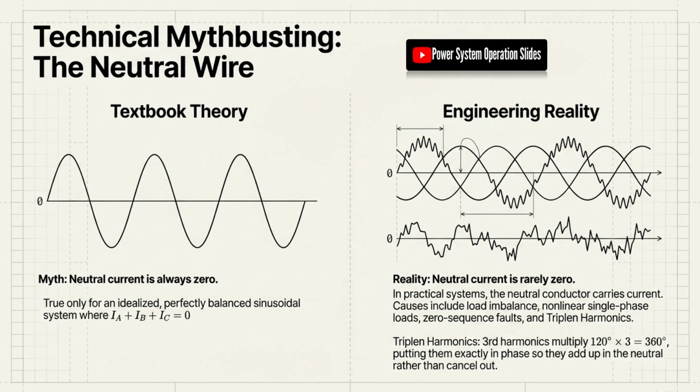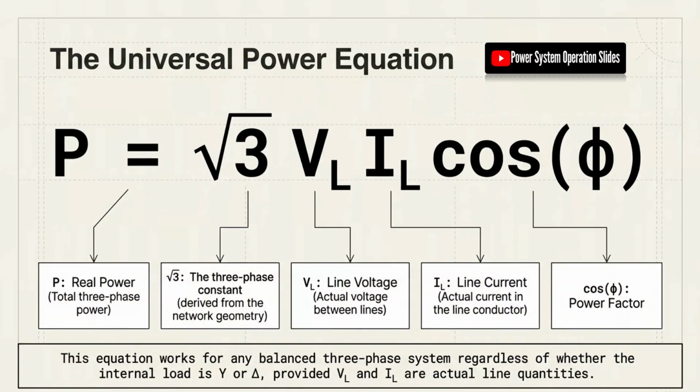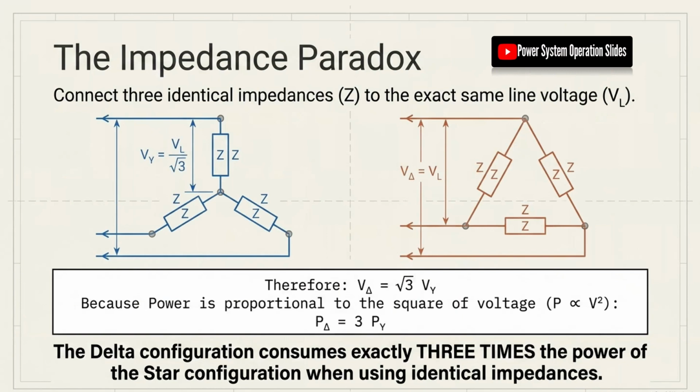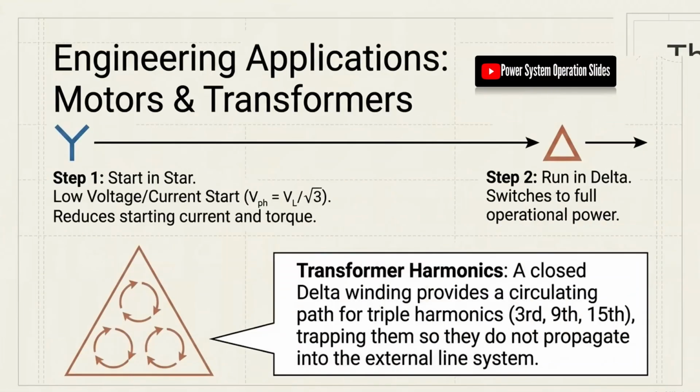However, ungrounded systems also create important risks. During a sustained ground fault, the voltage of the two unfaulted phases relative to ground can increase significantly. This increased voltage can place additional stress on equipment insulation and increase the probability of another fault occurring. A second ground fault can then develop into a much more severe phase-to-phase fault. Modern practice therefore frequently uses controlled grounding methods such as high-resistance grounding, which limits fault current while allowing protection and monitoring systems to identify the fault and support corrective action.